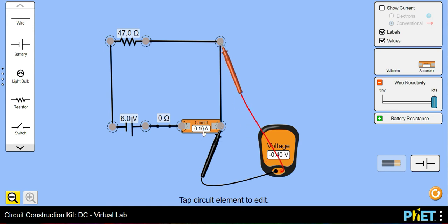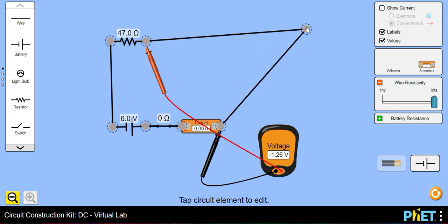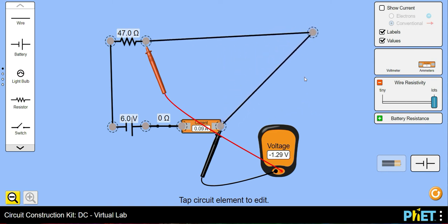You've already noticed, should have noticed, that there's a difference in the current, and that's because there is now a voltage being dissipated across that piece of wire. Worse, the more wire, the more voltage. If I even just stretch this, it climbs dramatically. That makes it pretty tough to do circuits if you have to start measuring the traces in the wires.